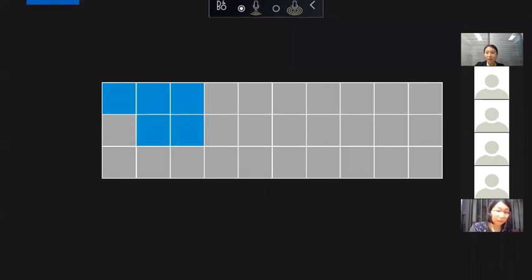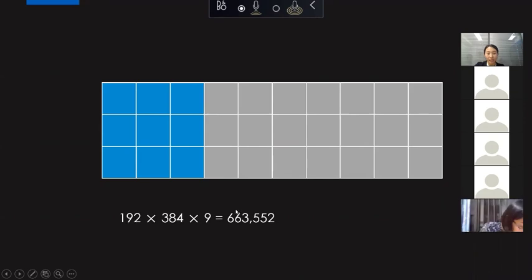After we calculate the loading capacity, we find if we connect 9 cabinets for each output port, the loading capacity is 660,000 pixels. It is beyond 650,000 pixels. So it is too much, cannot work.